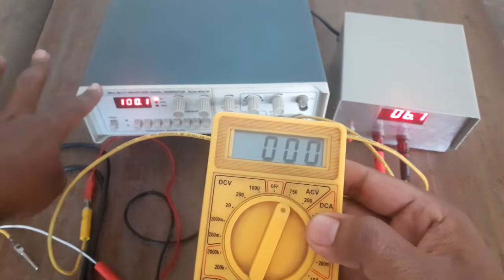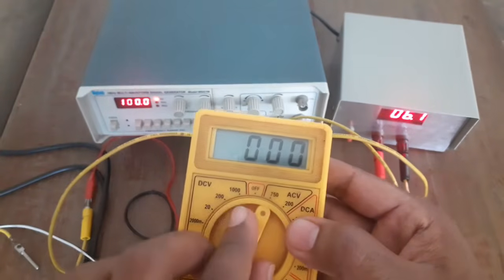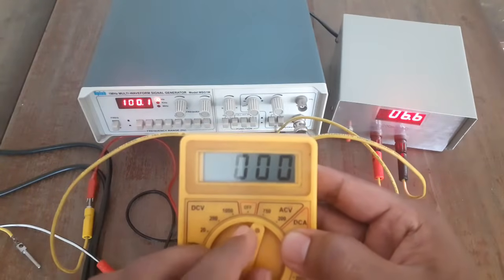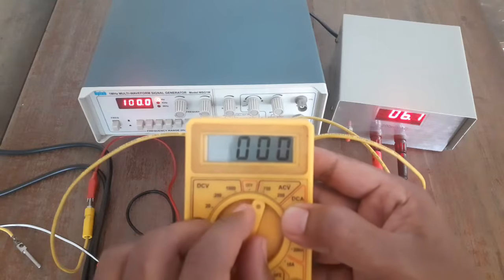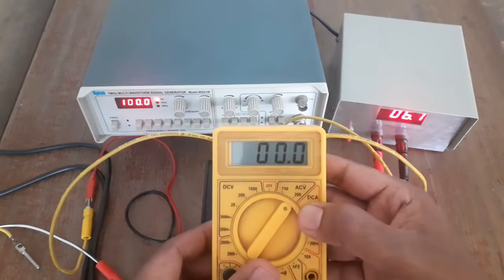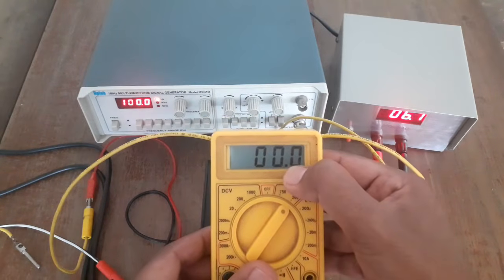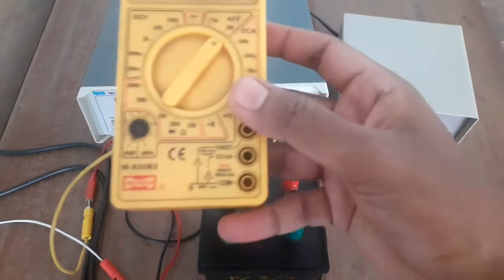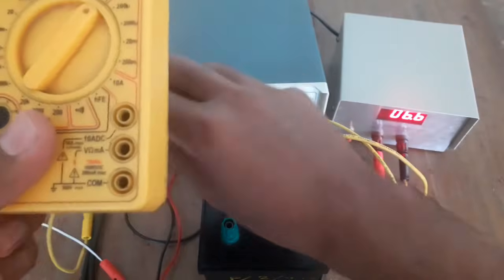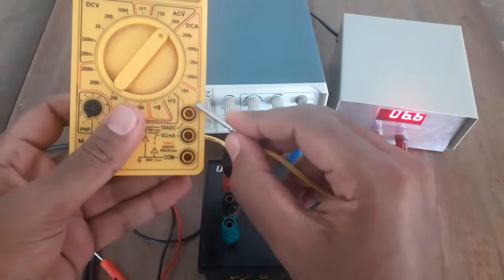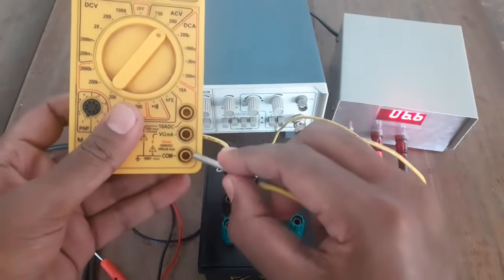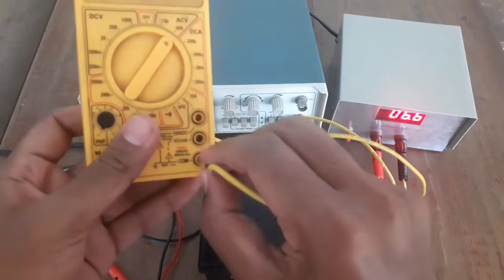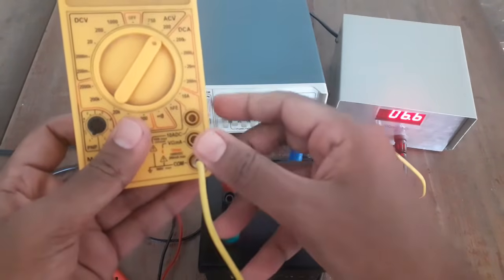And you just saw that the voltage is around 20 volts, within 20 volts. So you don't need to use 750. Just use this minimum one, the 200 one, so that you will get more accurate readings. Fine. So now how to connect this one? Connection should be taken through these things. There are three inputs for this. The first one is common, it is a compulsory connection, you should always take from here.